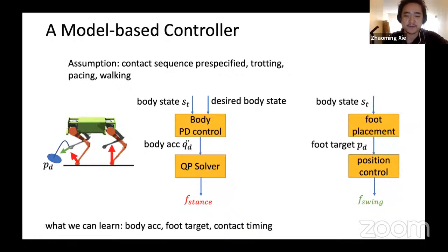But because we are doing reinforcement learning, the policy during training sees all the possible outcomes that will happen, and then it will make control. Even though the control command is only applied at the current time step, because it is coming from a reinforcement learning policy, it's able to look further ahead instead of just a simple one step look ahead. So it's a more efficient way compared to an MPC solver, which will require you either to have a reference trajectory over time and then linearize it, or to solve a nonlinear optimization problem, which can take a lot of time. So it's not real time anymore.